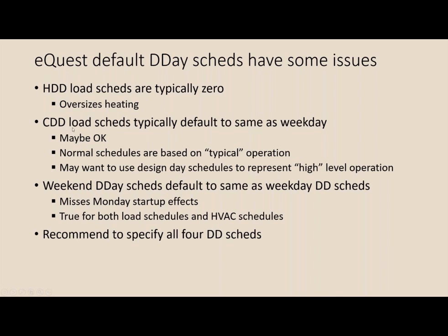For cooling degree day load schedules, they typically default to the same as the weekdays, which might be okay. That's at least in the ballpark of what real typical operation would be. But you may also want to define alternate design day schedules that use a higher level of operation for cooling design days.